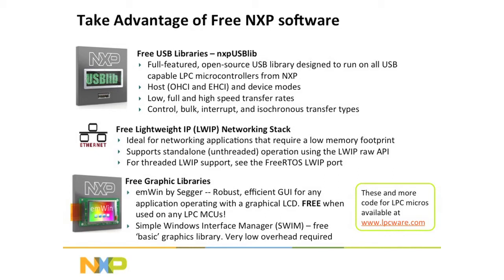And it's particularly targeted for small microcontrollers, and it has a very small footprint. It's very configurable. You can get it down to as small as, I think they say, between 4 and 9K, depending on which options you include. So you can use that either standalone, or you can use it with an RTOS. And we have support for FreeRTOS in the software packages that we have up on the site.